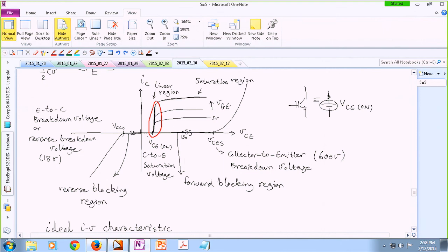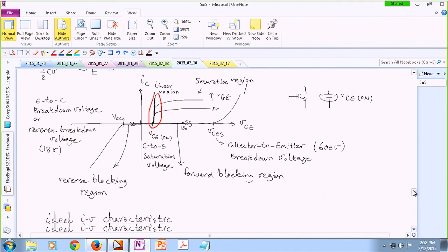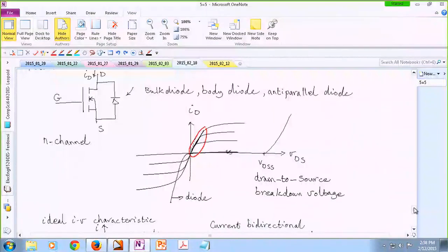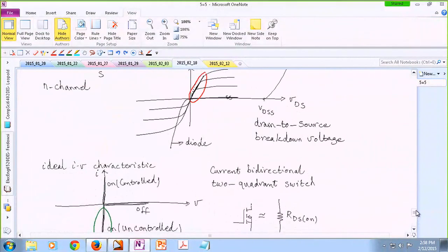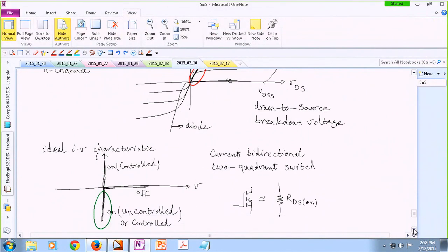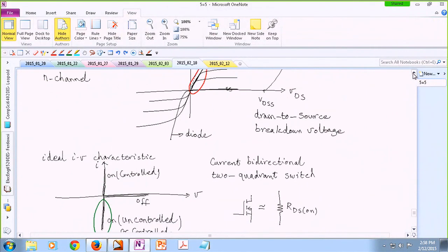Something like this. You didn't say much about a reverse voltage on a MOSFET. Is that problematic? I mean, if let's say it's faster than the diode can react, would it damage the MOSFET? Or usually not? The mentality is that because you have the diode here, you should never expect your MOSFET to block any negative voltages. So in the system that you're designing, you're trying to avoid that scenario, because as soon as you tend to get there, the diode is going to turn on.